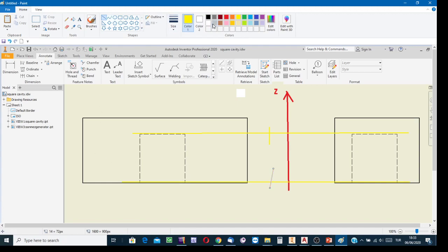Okay? For instance, on the left side view here, if there were such a part, not this hidden rectangle, but instead of a hidden rectangle on the left side view, if we had such a visible rectangle, then I would say that this means at the back side of the object there is a rectangular prismatic extension.